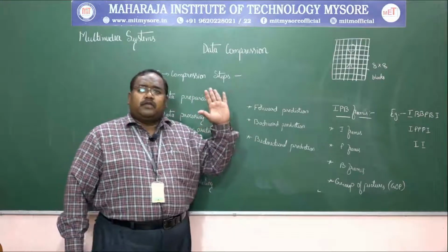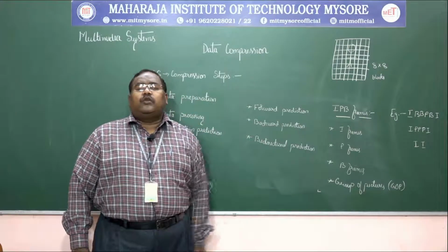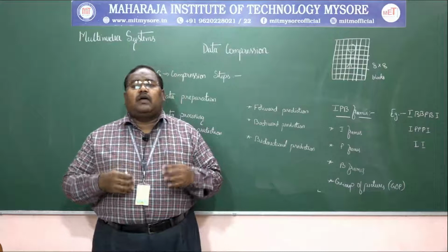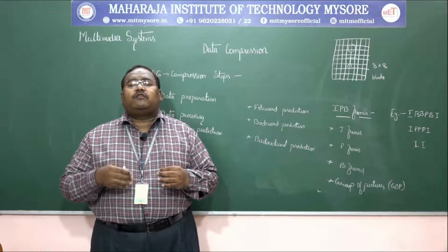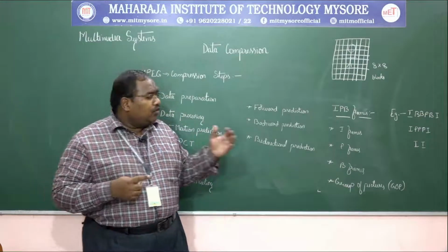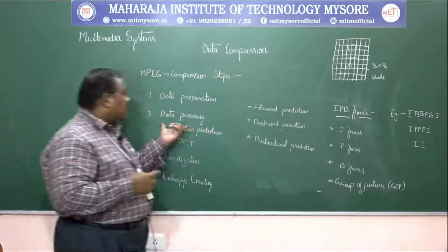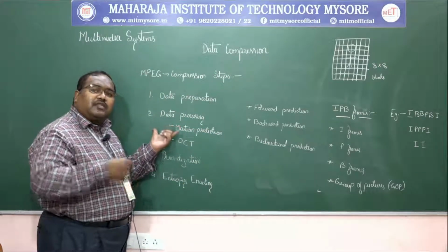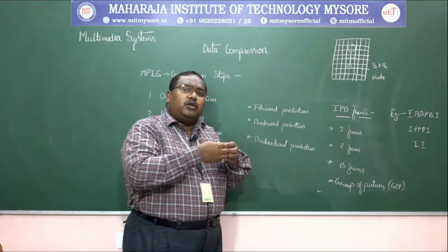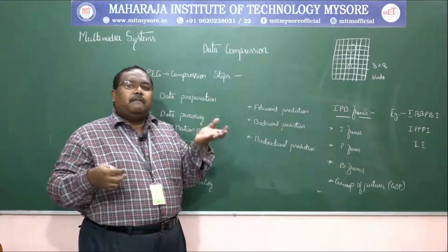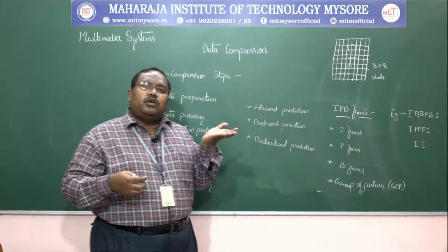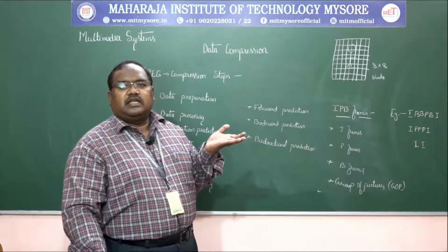So this would happen with respect to stage 2. When we are dealing with an MPEG decoder, many times it needs to have a buffer, because extra frames of data are added for the display property. During processing, we need an extra buffer because we are calculating the previous and the future frame. So, in order to make a good display property, temporal space is needed during the decoding of the frames. So a good, or a huge, buffer is always suggestible.